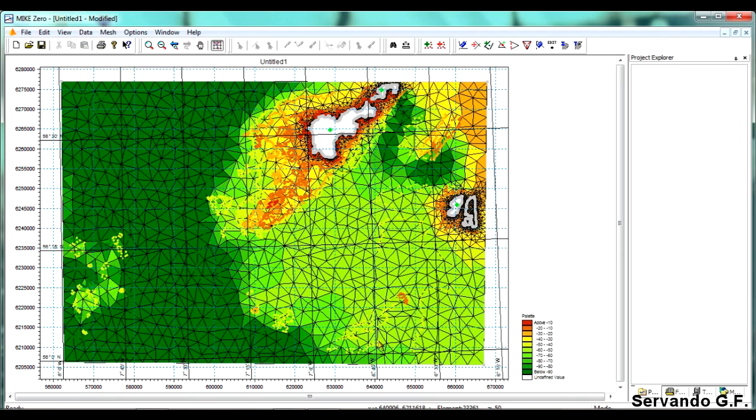This is the interpolated bathymetry. Here it is showing the original data. See? And well, I have to say that it doesn't look very good. Why? For two reasons. First, our mesh is quite coarse, so it has to give a value to each triangle, and this is what it is showing. And also, the palette here is quite coarse too.